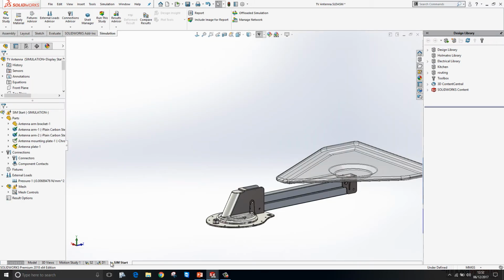A common workflow when working in simulation is to design a part and then test that part using the simulation tools. During that process, you will create fixtures, mesh refinements, apply loads, and so on and so forth. You may then want to take that model and test it in its assembly environment, and you'll go through the process of recreating those fixtures and loads at that level, which can lead to user errors.